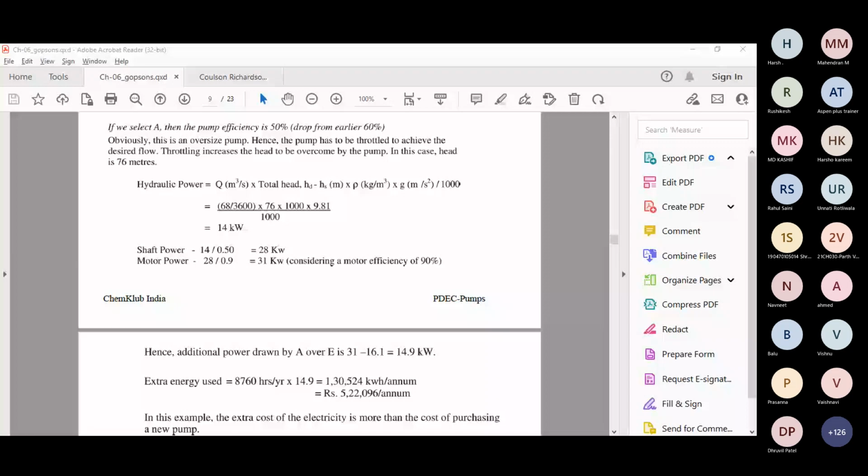Sir, as you said, in heating systems, there may be a possibility of pump surging due to the temperature of the fluid in case of hot oil. Why? The pump is designed for that particular temperature only. A hot oil pump will be designed for that particular temperature, and its NPSH will also be accordingly. What I have to do is run at the best efficiency point, that is the motive, right?